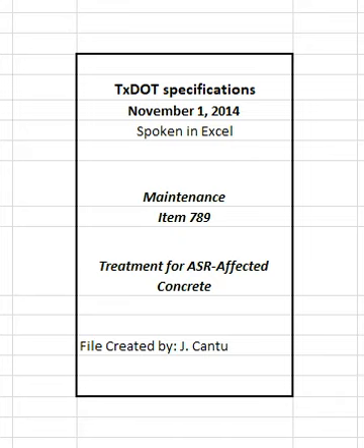Use water-injected abrasive blasting, less than 1 GPM of water, to clean the surfaces if dust control measures are required. Brush off remaining residue before applying surface treatment. 4.2 Application of penetrating sealer/primer. Apply the penetrating surface treatment in accordance with item 428, penetrating concrete surface treatment. Work the surface treatment into cracks for maximum penetration. Follow the manufacturer's recommended application rate if it is higher than specified in item 428, penetrating concrete surface treatment.